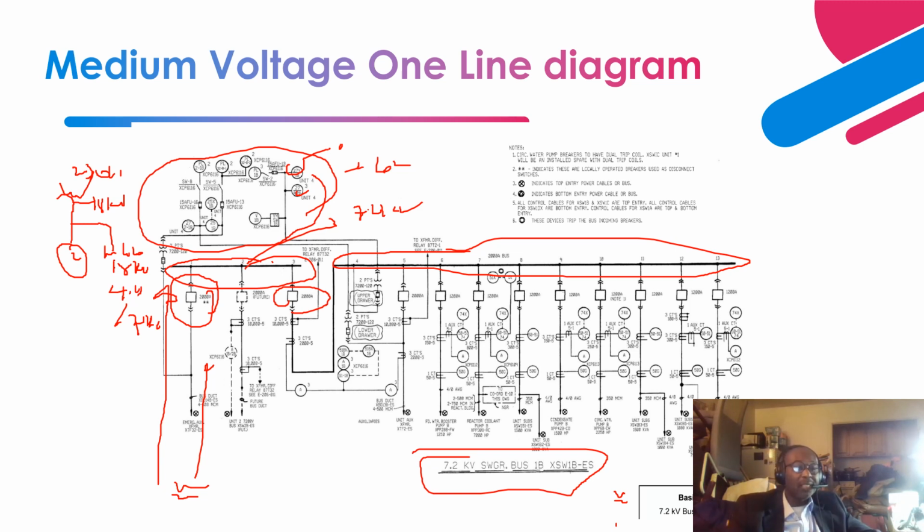Based on detection of the voltage, if there should be an under voltage condition on one bus, you can basically trip this breaker and close this tie breaker first, then trip this incomer breaker, to be able to transfer all the loads onto this bus. Okay, so over here are all the relays that are tied to this section of the bus, right?